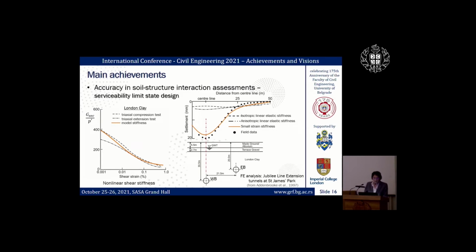And this is where the recognition of the nonlinear stiffness of stiff clays, like London clay, came into play, calibrated on the experiments performed on London clay and taken into the finite element formulation and into constitutive modeling of London clay, showing as one example here the settlement trough above one of the two tunnels at the location of a park.